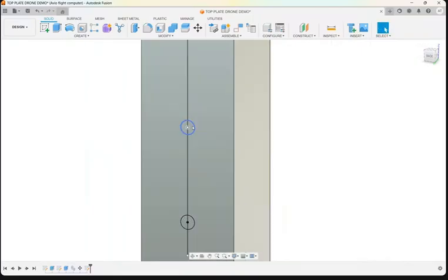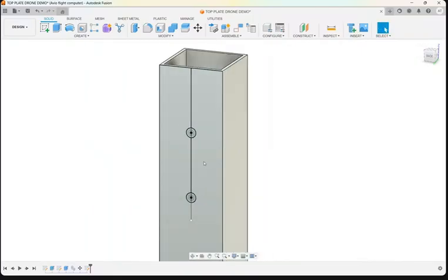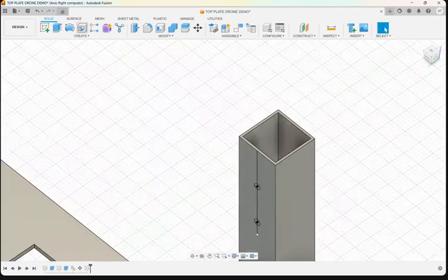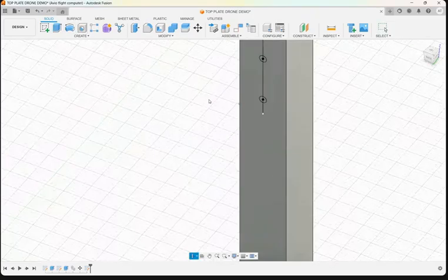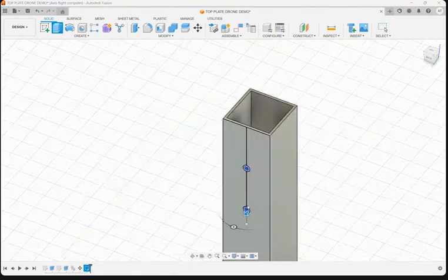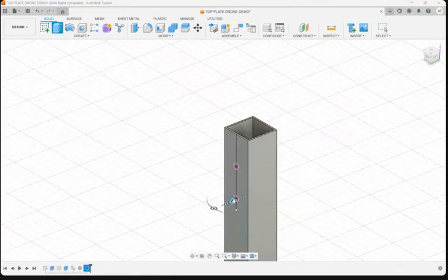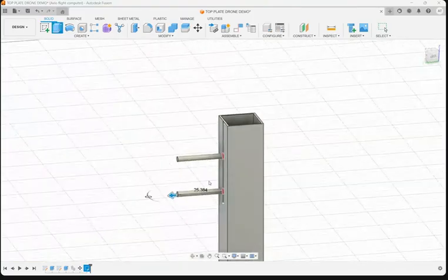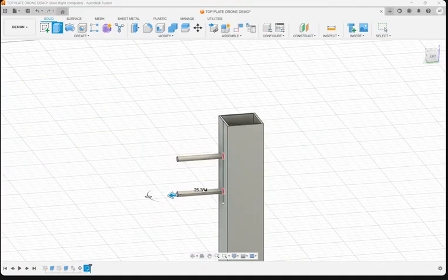Now I have got the circles over here. Now I have to extrude. When I select the extrude option and select these circles, if I pull the arrow at this point, these two circles don't go hollow but instead form a rigid 3D body. This is extrusion.